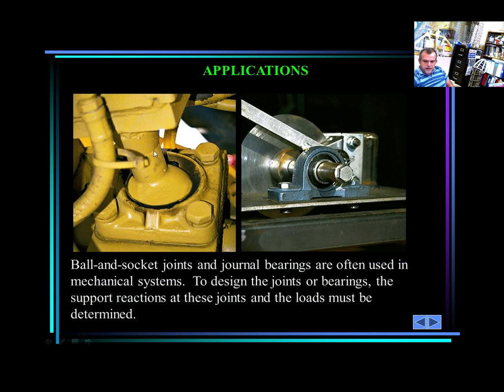Application, well, once again, this is a ball and socket. Theoretically, this thing can rotate in any direction. This is like the old joysticks in the video games, in any direction. But you have 3 force reactions restraining all the translation. But the 3 rotations are free, so that type of support produces 3 reactions.